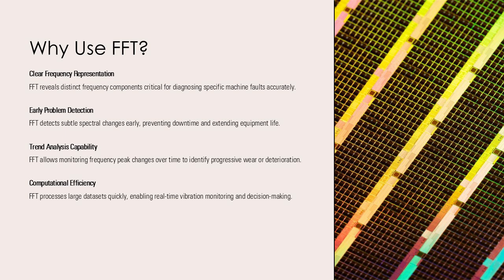Second, FFT enables early detection of problems by revealing subtle changes in frequency spectra that might not be visible in time domain data. This proactive approach helps prevent costly downtime and extends equipment life. Third, FFT supports trend analysis by allowing engineers to monitor changes in frequency peaks over time, which can indicate progressive wear or deterioration.